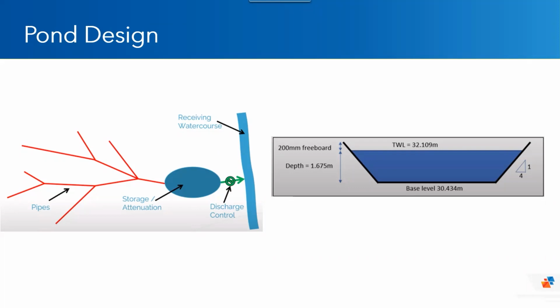And what we're going to do, first we're going to design the pond based on our criteria in a subdivision, and then run this for a number of storms and look at the pond volume. After that, we will introduce some of the sustainable drainage systems and then rerun the analysis, take a look at the pond volume and see if that can be reduced.